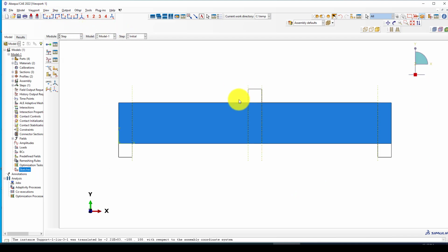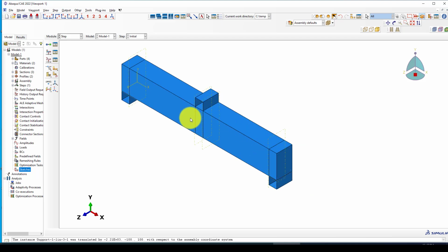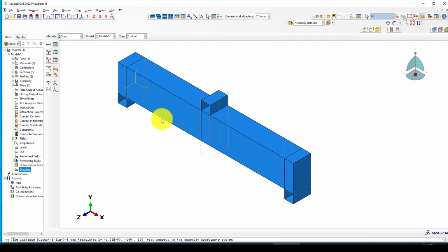We have a choice to conduct static and dynamic. I should say why we're using dynamic explicit or standard. Mostly for this case, the concrete is a very complex nonlinear material, so we should consider a solver that can solve very large nonlinear properties.